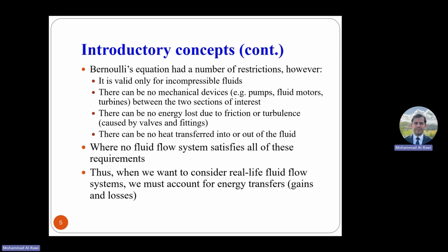Bernoulli's equation has its own restrictions. For example, it's valid only for incompressible fluids. There can be no mechanical devices, so it's assumed there is no pump and no turbines between the two sections of interest, and it also assumes there is no energy loss due to friction or the turbulence generated through sudden enlargement or contraction or fittings such as elbows or even valves.